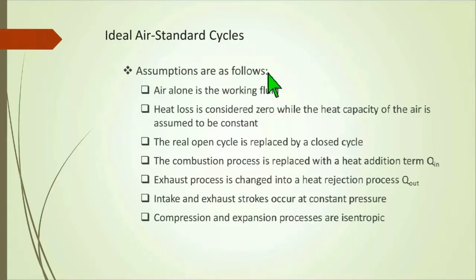Assumptions are as follows. Air alone is the working fluid. Heat loss is considered zero while the heat capacity of the air is assumed to be constant. The real open cycle is replaced by a closed cycle. The combustion process is replaced with a heat addition term Q-in. Exhaust process is changed into a heat rejection process Q-out. Intake and exhaust strokes occur at constant pressure. Compression and expansion processes are isentropic.